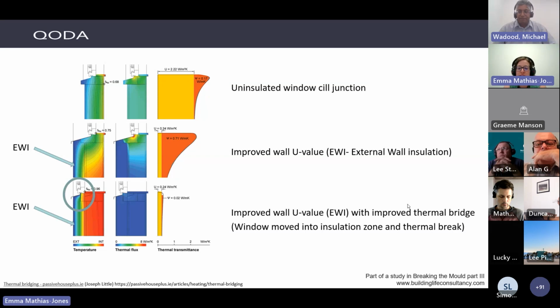Yeah. But if you're not calculating your thermal bridges, maybe that's something building control practitioners should be asking the question about: have you considered the thermal bridging within the U value calculations and within the overall DER TER calculation? Potentially, particularly for dwellings, you almost need to calculate them now, because of that default. The difference between your notional and actual building is so big.